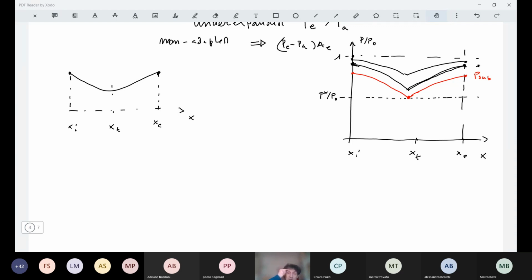So we can saturate the converging diverging nozzle, because of this converging diverging shape, even if the ambient pressure is higher than the critical one. If it were only convergent, we should look at this abscissa, and so the ambient pressure has to become equal to critical to reach saturated conditions.